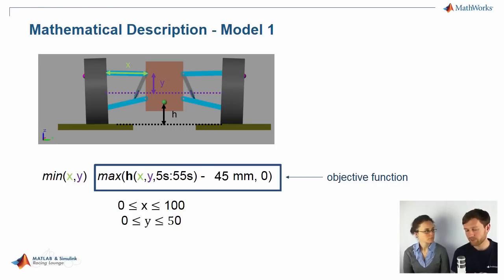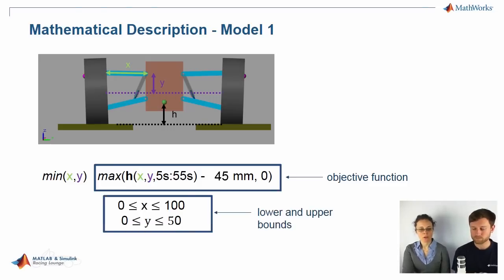And giving that preliminary information is fine, because we know that the arm does not have negative length, and we know that it's not longer than 1 meter here, 100 centimeters. So in case we know it, we should give it to the solver, right? Exactly. What we call this kind of constraints are really the simplest constraints, the lower and upper bounds on the variable values. Got it. And if you have them, please just add them.